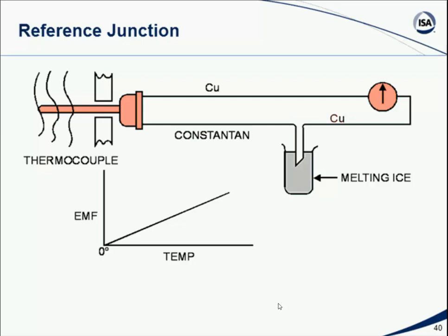If I were to take two types of metal, and in fact there's a type of metal we all know called copper. There's another type of metal called Constantan, and these two metals have different enough electrical properties that if we create a thermocouple, in other words, crimp a pair of them together at one end and stick it into a heat source, here we're saying thermocouple, and then take the other end of those wires and crimp them together and stick them into a reference, like melting ice. And we know that ice melts and it will sit there generally at a 0-degree temperature.